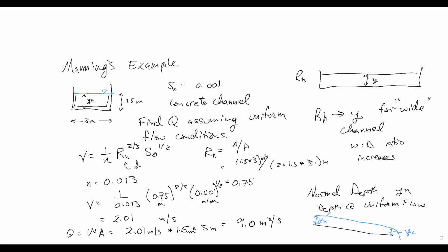So the flow is getting faster and faster, not really accelerating, but in the x direction you could say it's accelerating as it gets over this pour point. So at some point upstream, if everything's the same and prismatic, we can approach this normal depth. So that's where this calculation could work.